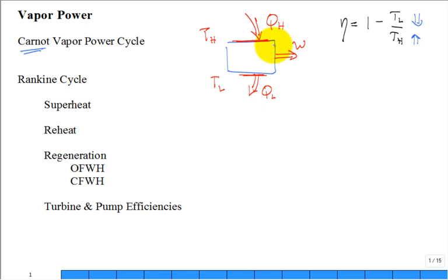What we really do is we look inside the black box of the heat engine and we say, you know what? That's a boiler. And that heats up water and converts it into steam, and then we go to a turbine which is connected to a shaft. And then we go to a condenser which rejects heat, and then we go to a pump or compressor, call it a pump. And so we could look inside and say, oh, this is actually how it could operate with a system with 4 components and the fluid flowing in a continuous cycle through those 4 components.